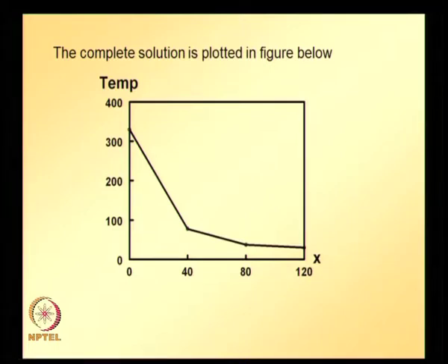So, now this is one application of the general one dimensional boundary value problem that we are looking at, and here if you see this problem, at node 4 temperature is specified. Instead of that, we can also have a convection boundary condition prescribed. So, in the previous problem at T4 we had an essential boundary condition specified. Now we will look at the case when a natural boundary condition is specified at node 4.